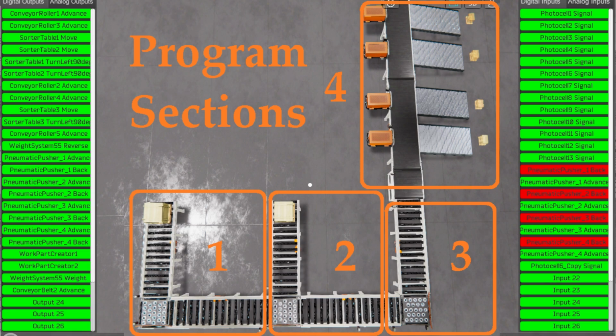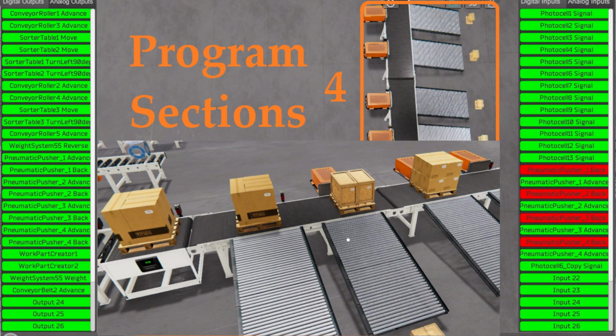Now Section 4 will control the weigh stations and exit ramps. When no box is detected on the weigh station, the box at the end of conveyor 5 will be moved onto the station. When a box is detected at the station, a timer is used for 2 seconds to allow the weight to be read.